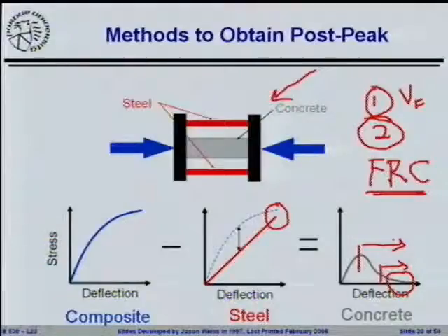And we'll spend a lot more time talking about fibers at the end, and we'll actually start to go through some calcs where you can bring some of this into your design. But there's a lot of work in Europe right now where they're actually getting rid of steel in a lot of their slabs for, let's say, light commercial residential types of apartment buildings, and they're designing them with just steel fiber reinforcement in them. So there are some benefits in those directions.